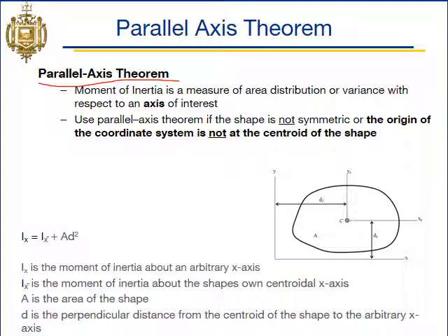So in this big shape here, we have our centroidal x-axis, and we can use the parallel axis theorem to calculate the moment of inertia of this big blob shape around this parallel x-axis here. And we'll see why we need to do that in the next few slides.